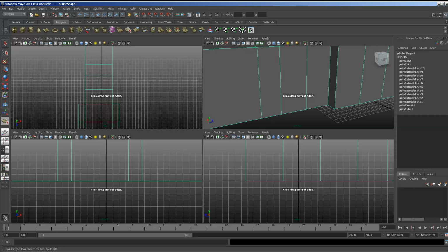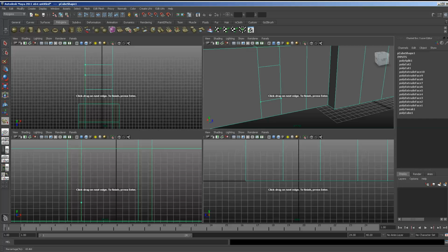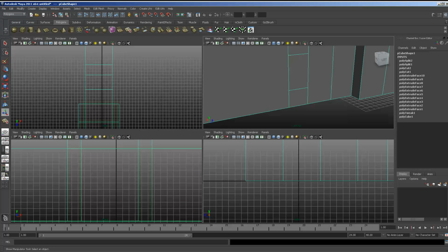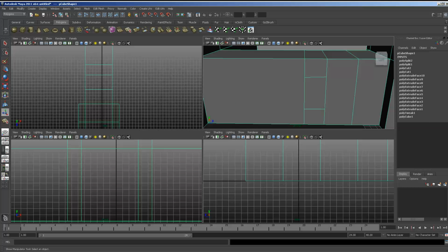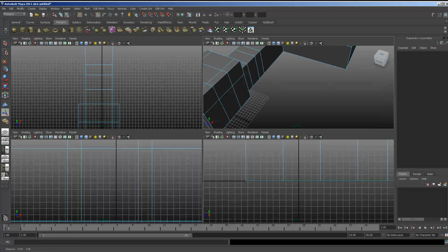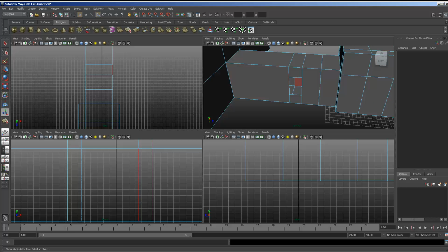And you can also use the split polygon tool. You don't especially need to end up with 4 polygons, since Unity will divide it in triangles anyway. Something like that. That's a window, I'd say.